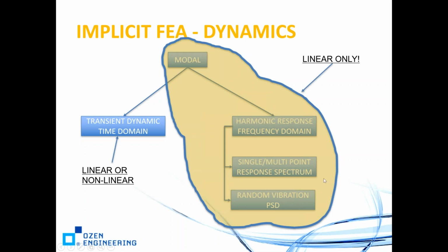So please keep in mind, whatever we see on the right-hand side, including modal analysis, harmonic response, single point or multi-point response spectrum, and PSD, these simulations are linear only. And what do we mean by linear only? That means there's no nonlinearity. However, if we solve the problems in time domain, then we can solve it either in a linear manner or in a nonlinear manner.